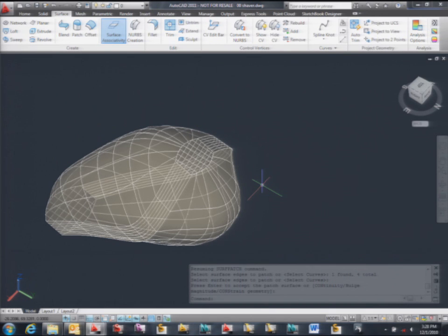I mean, you can do that, but for example, you can also add a guide. You may want to say, I want to do G0, but I also want, if this is my one surface and this is the other, I want to do a bump like this. You will never get that with a blend. So it's kind of different ways to get to the same place. Why would you use a network surface as opposed to a loft with two guides if you're talking about just four edges? No reason why. Unless you have a third or fourth guide in the middle, and the loft cannot make a loft with many guides, just on the ends. Am I clear? Fine? Okay.